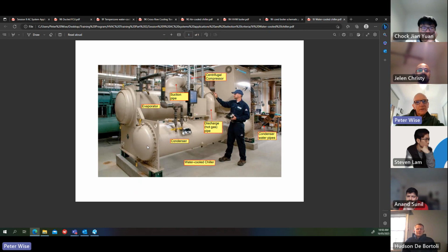So you don't necessarily need a marine water box. And if it's specified, it's worth looking at whether you can do something else, because a marine water box might cost per chiller, might be another $5,000. They're quite expensive. Anyway, when we talk more about chillers, I'll go through that in more detail. There's so many things you can do with chillers and so many different options.